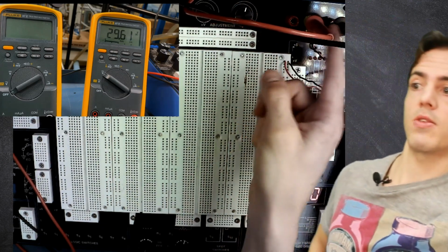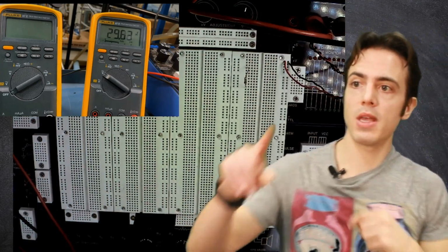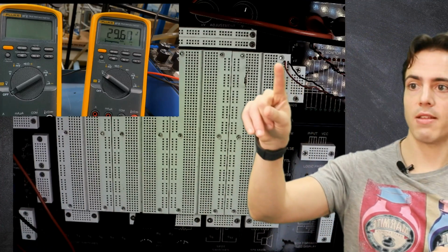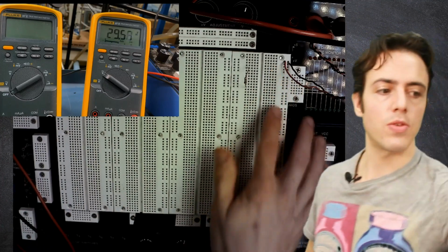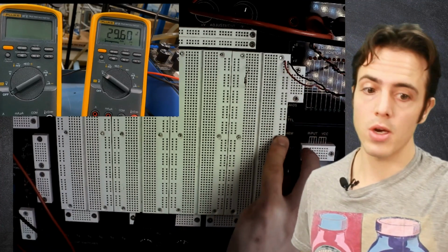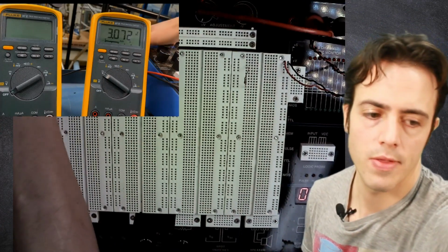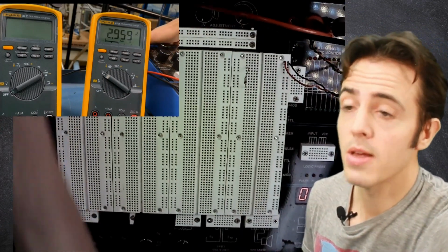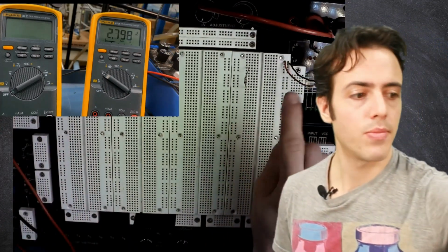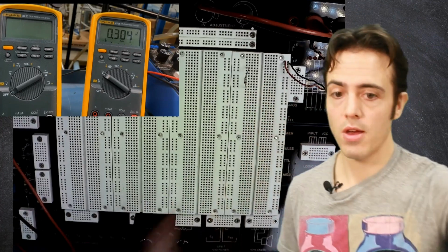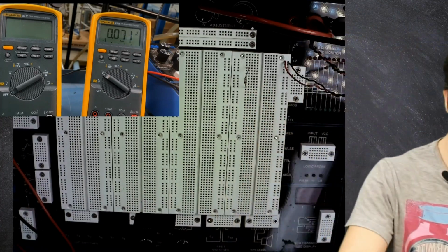30 volts of DC between these two terminals over here, which means that those cables that are coming in have connected up here and are now supplying these two columns with the two voltages that I had selected. So turn this right down, and then I'm going to turn this off. Now we're going to wire a circuit up such that I am supplying this resistor with that voltage. And I'm going to do that by connecting these jumper cables.